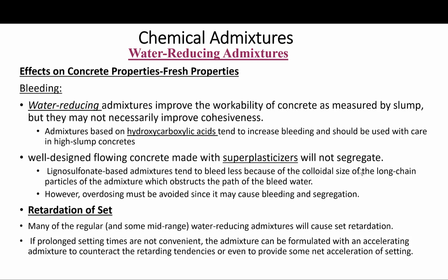I thought, based on my reports, it was the lack of appropriate testing and trial batches before the use of admixtures, or it could be due to the addition of admixtures at will without control. So okay.